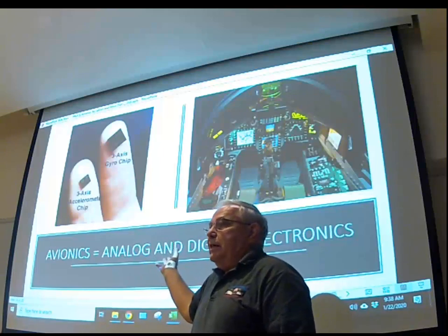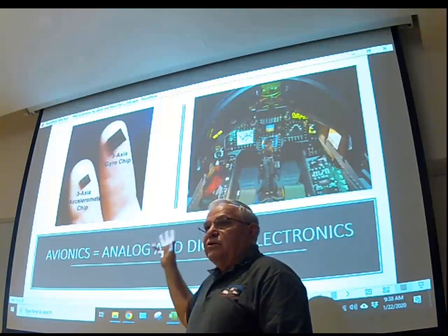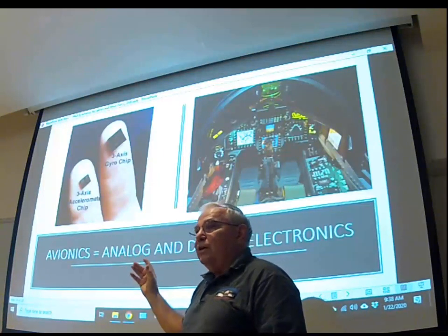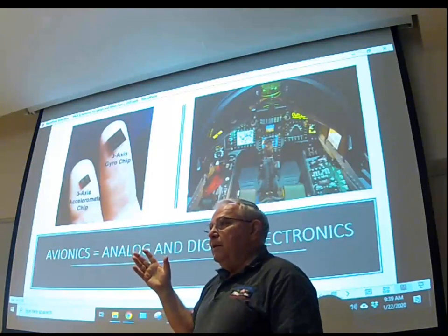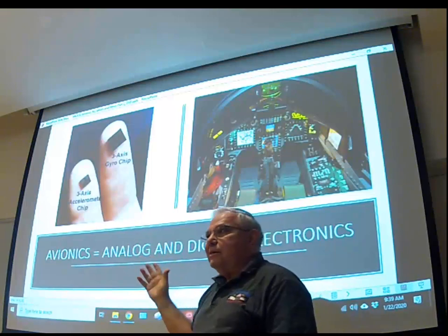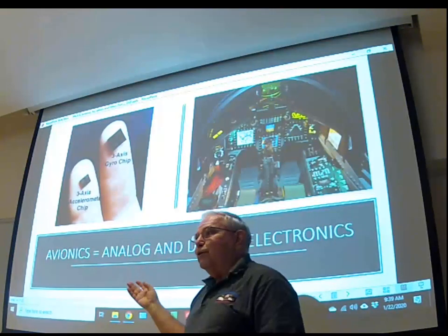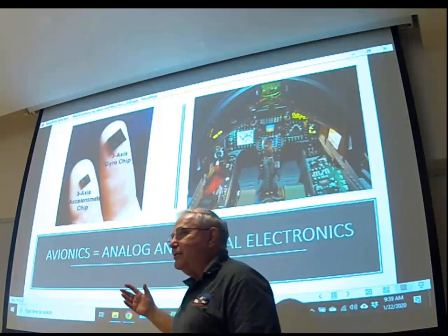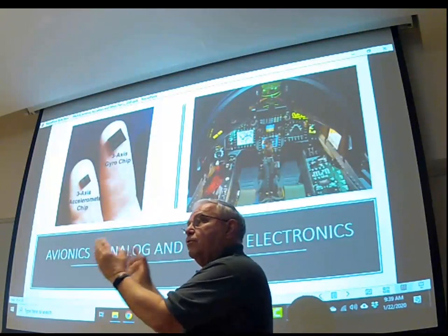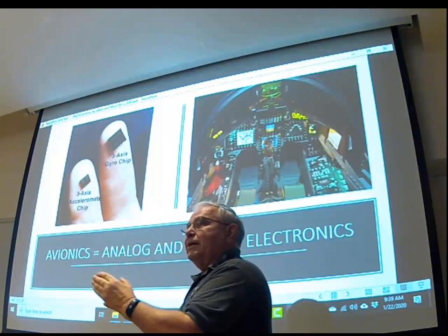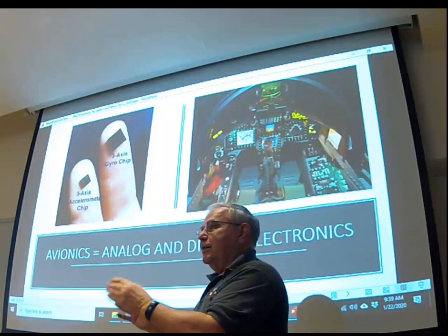Use our airport as an example. Our airport runway is 303 degrees, right? That's relative to the Earth's rotation, fixed axis, never changes. The variation right now is kind of given as 13. Maybe it's 14, maybe it's 15. The magnetic course is moving. So if you subtract the variation, you'll get runway 29. That's the name of the runway. The name of the runway is this magnetic heading. That's what a pilot would fly to line up with the runway.